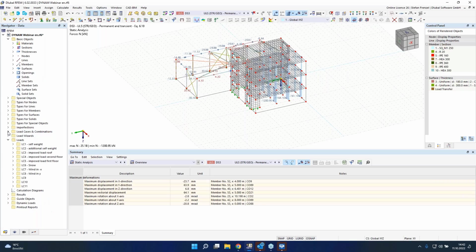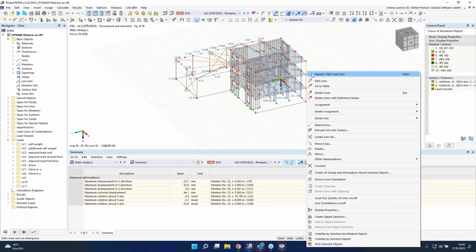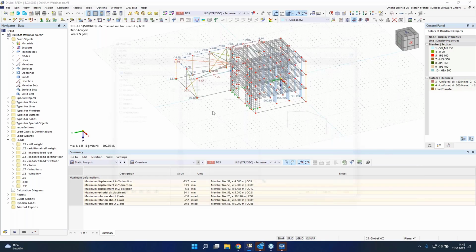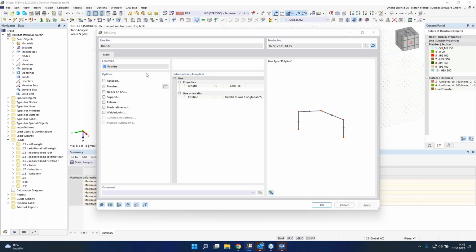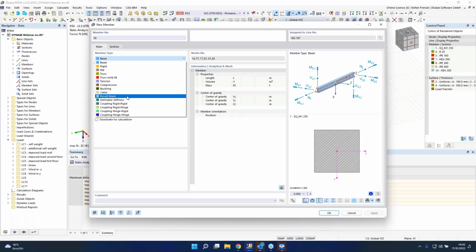And therefore we have here a new add-on, because otherwise, in RFEM 5 or here in RFEM 6, it's also possible to use a result beam. That means I have to create a beam here, through added lines. Here I'm able to create a member, and I'm also able to say a result beam. Here I can integrate all surfaces and all members of the structure to member internal forces. Then I can compare the shear force of this member with these two result combinations or design situations.